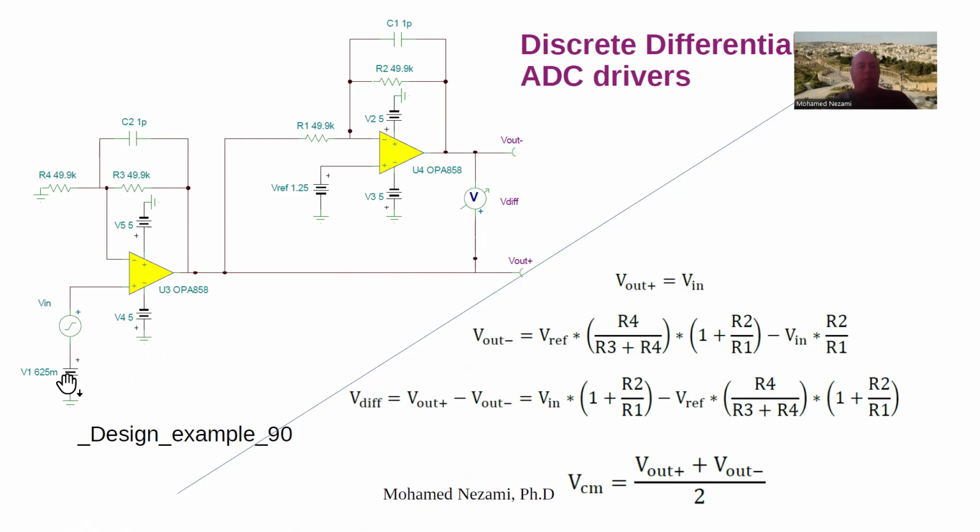And then I have a little DC offset in this case, 625 millivolts. That here gets gained by 2, it doubles. Oh, I'm sorry, the gain in here, yeah, it's 2. So this one in here doubles, and that's 1.5 volts in here, and 1.25 in here. And that's why we're using 1.25 as well in here. And this one, same thing in here, so this ends up 2.5 volts.